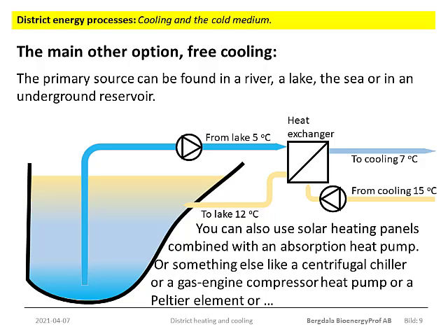And then you lower the pressure and allow the condensate or the compressed cold gas to flash, that is, to evaporate or to expand into a low pressure chamber. The energy uptake during the evaporation or the expansion is used to cool the coolant, and then the gas is compressed again. This is quite a common type of system.